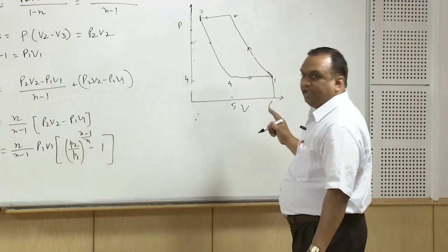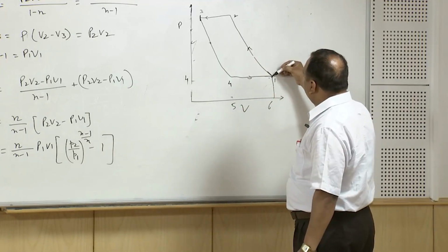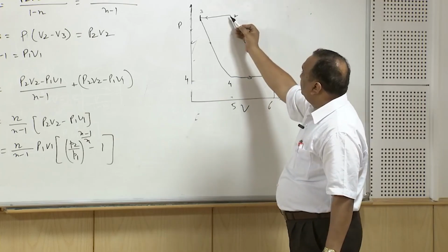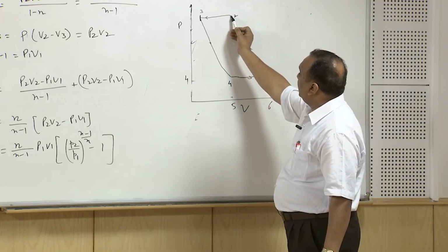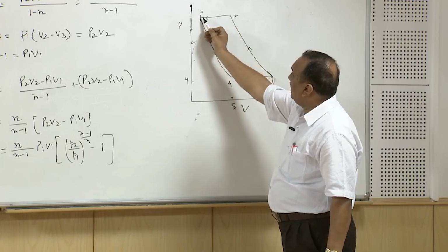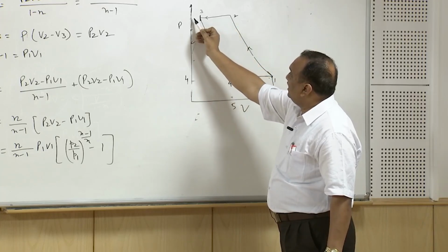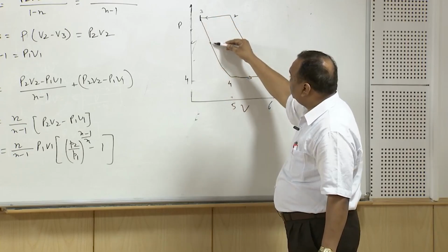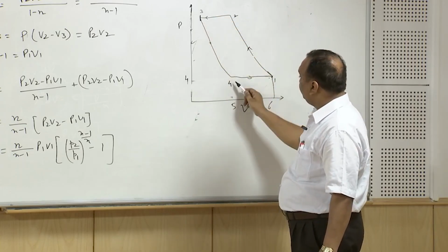So this is the actual cycle, where initially the compression takes place at the bottom dead center, then after state 2 the exit of vapor starts from the compressor and terminates at state 3. At state 3 we have compressed vapor. This compressed vapor expands. The system behaves as a closed system up to state 4.